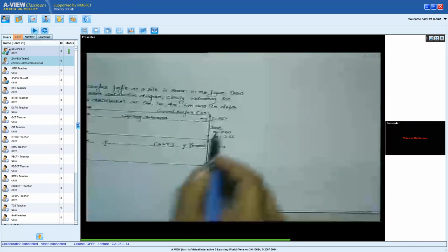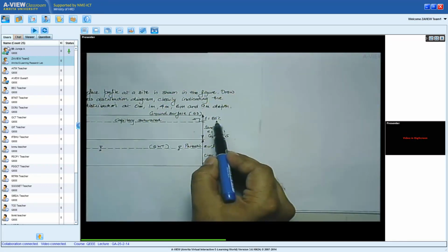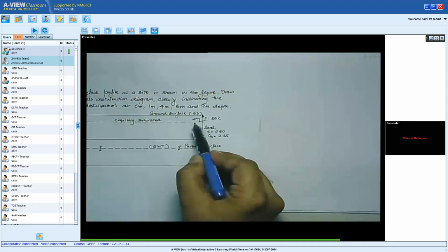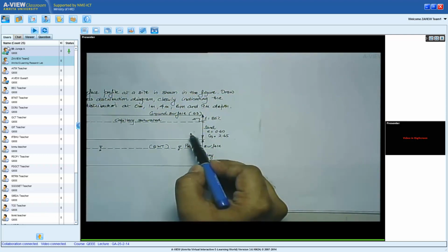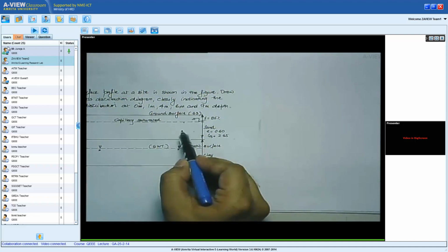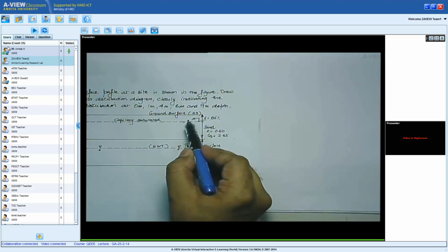Okay. So the first part is, over here you have been given the void ratio of the sand, the specific gravity of the sand. So below this broken line, that means from the broken line to this level, the sand is saturated because of capillary. The degree of saturation is 1. Over there, the degree of saturation is 0.85.